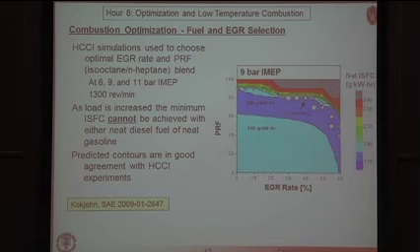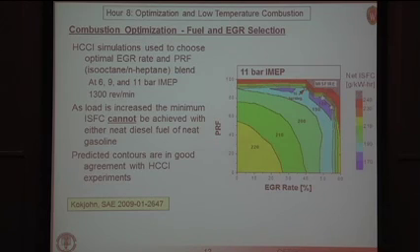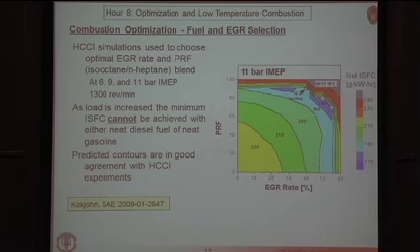So here's the 9-bar operating point. You see everything gets squeezed up here. Now your region of no operation is occurring at higher PRF numbers. Again, if you're running with diesel, you can see that to get to the small stars here, you're going to need a lot of EGR. But now you want actually a higher PRF, which would mean more gasoline. And then if you go to the 11-bar point, you see that now you really want to have a lot of gasoline, in other words, close to PRF 100. You're going to need some EGR in order to get to the low pressure rise rate point.